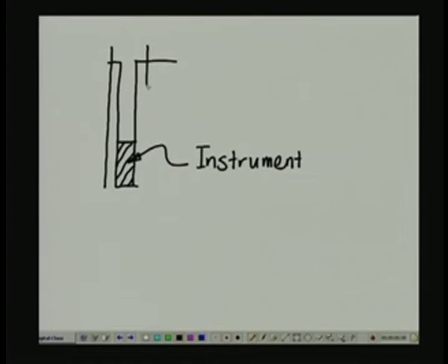constructed, is opened up, is advanced around the instrumented probe, and what you can imagine is that as soon as the annular drill bit, which is drilling the larger drill hole around the probe, around the instrument, goes past the instrument, there is a sudden change of deformation recorded within the instrument, and this deformation change can be related to the in situ state of stress.